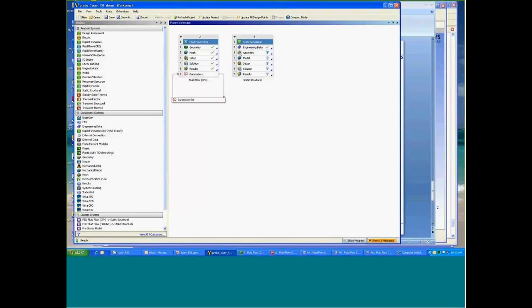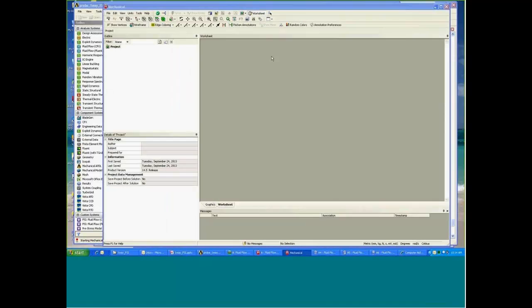Okay, and now I'm going to share this geometry. The static structure is going to use the geometry that you've seen previously. And in addition to that, I'm going to transfer the solution from the CFD side to the structure side. Okay? Now I'm going to look at the setup of the static structure in the mechanical system.